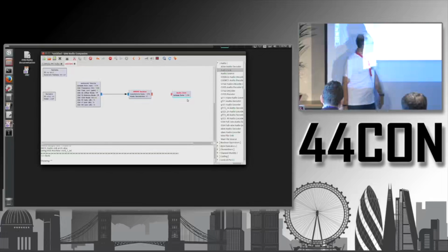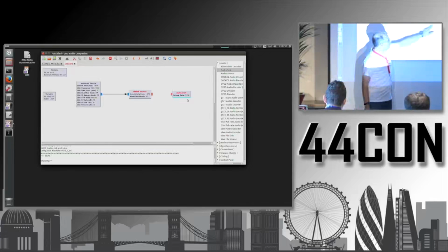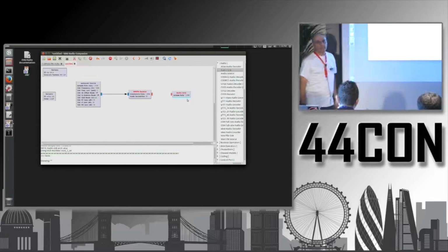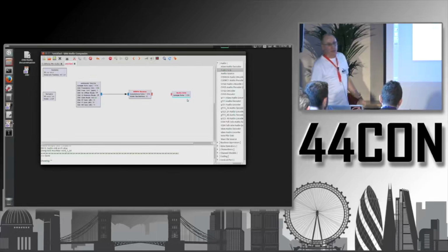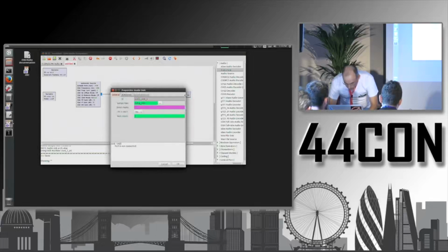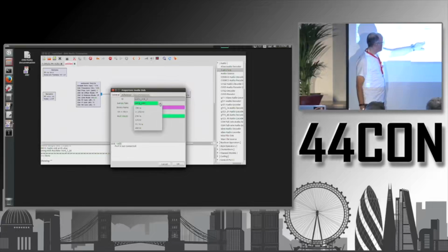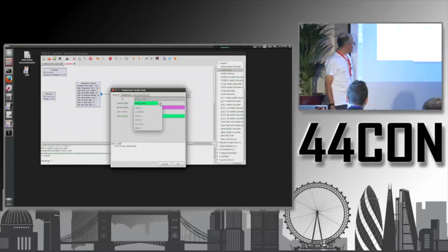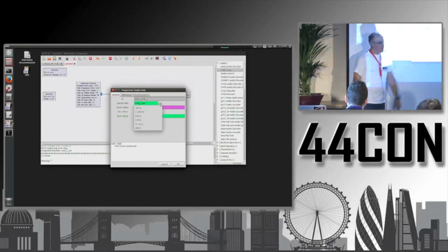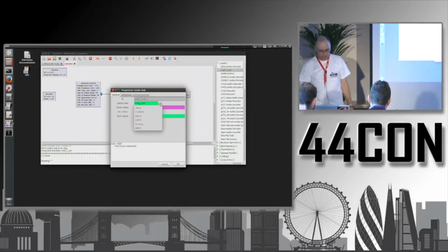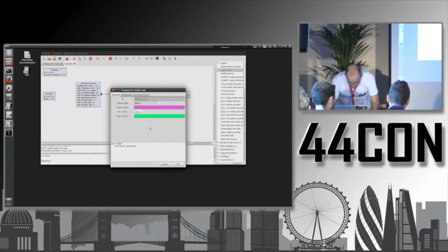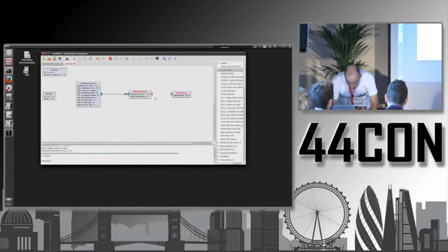Orange, so we can connect this one. You can see the sample rate, 1.92 megahertz. That's way too high for audio. So you can double click this and open the pull down here. And here you can see 48 kilohertz is one of the proposed ones. And you also have the 44.1 from CD quality. So you can select this one and then just connect.